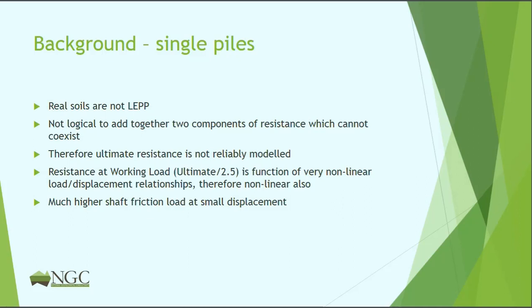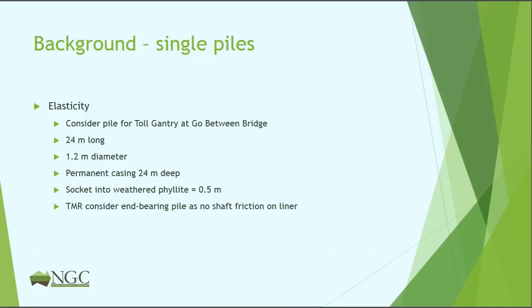And the resistance at the working load, where we've divided by 2.5, is a function of the very non-linear load displacement relationships, and therefore it's also non-linear. And we'll have a much higher shaft friction load at small displacement than the end-bearing component.